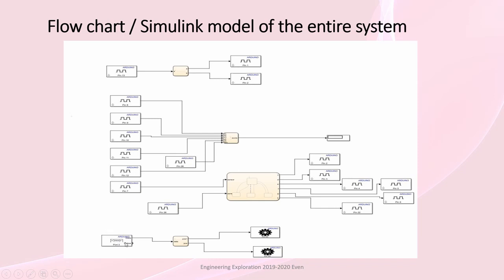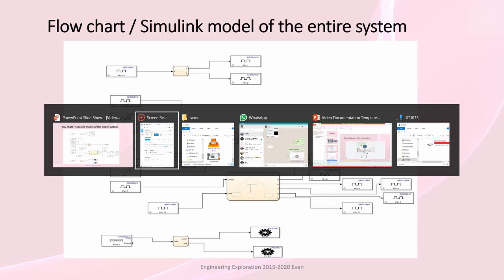Two pieces of information, one is L and one is R. L is used for controlling the left flipper from 0 degrees to 60 degrees, and R is used to control the right flipper from 180 degrees to 120 degrees.